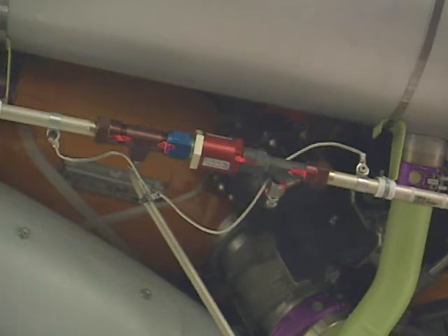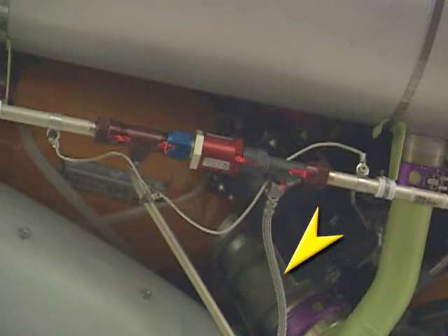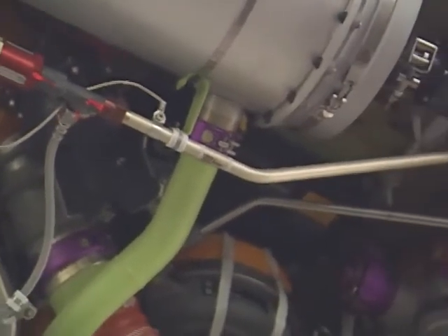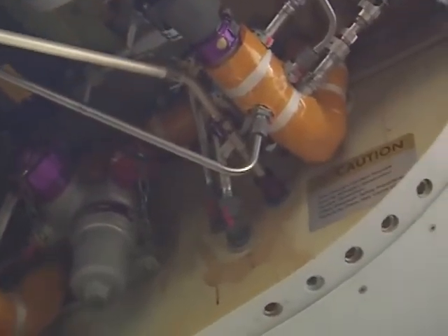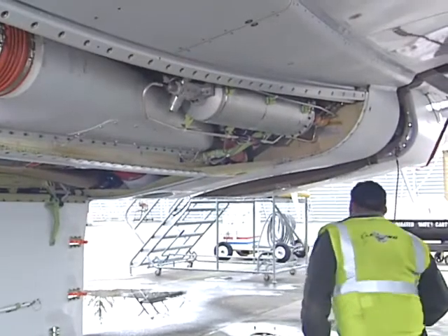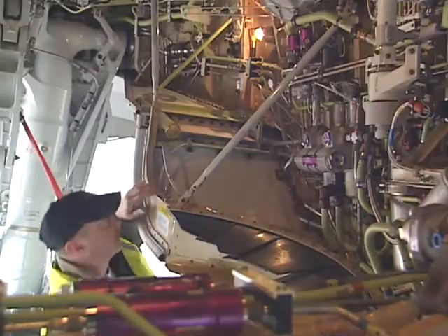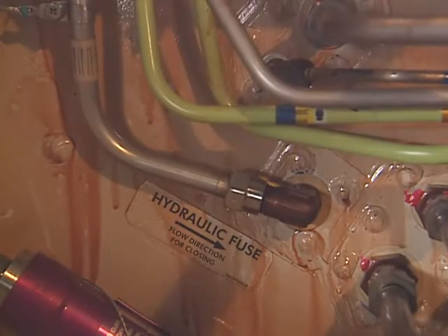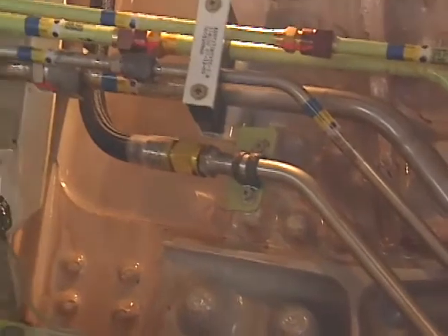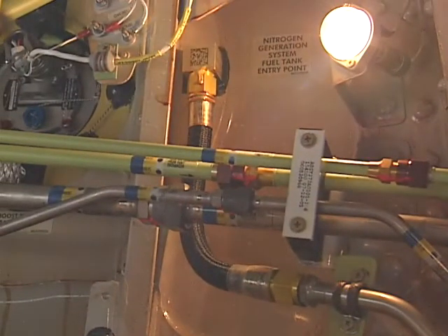Note, instead of the T-fitting, some models have a hose leading to a drain valve, and on other models, the hose is attached at a different point. See your maintenance manual for exact information for your airplane. From there, the DADS line continues aft and penetrates into the left main landing gear wheel well. Then goes up the forward wall of the wheel well and penetrates the rear spar into the fuel tank. The rest of the DADS components are inside the fuel tanks and will not be shown in this program.